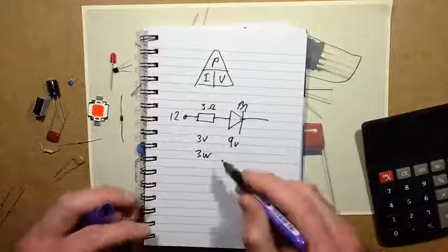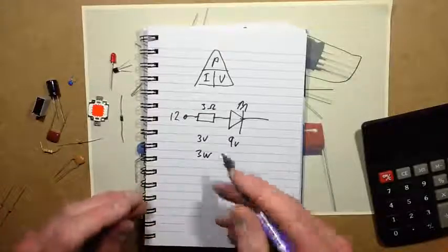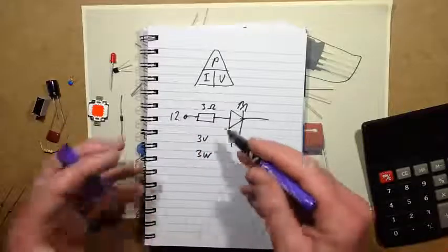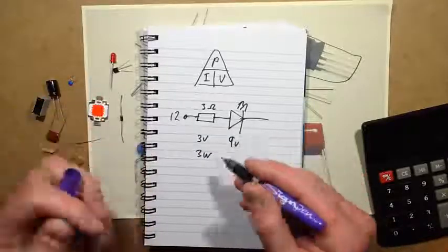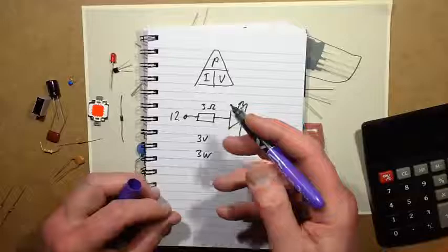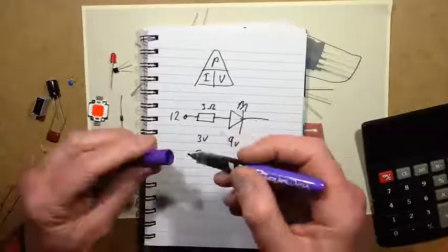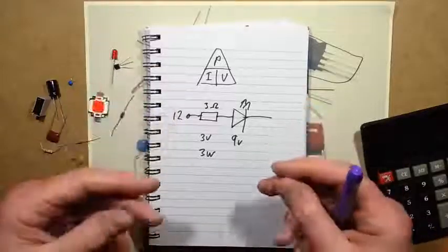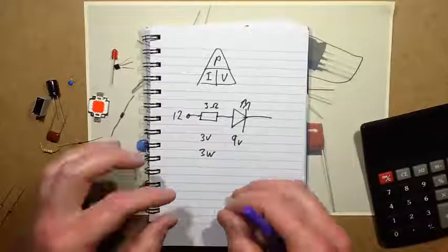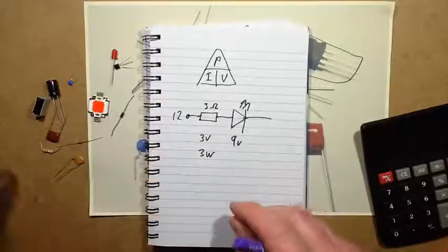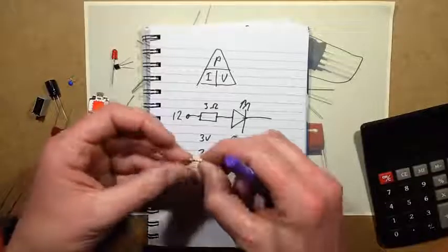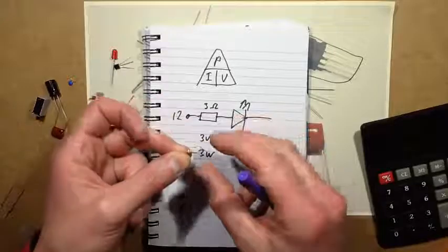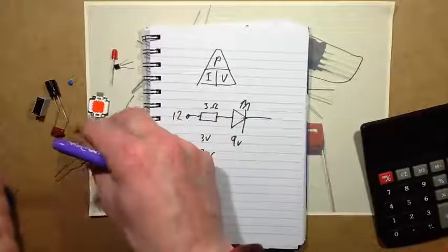But we'd actually be better choosing a higher power resistor. And it's not a terribly efficient way to drive the LEDs, but it works. It's very, very simple. I'd probably choose a 5 watt resistor because you want it to stay cool. You often see resistors that have just been pushed too far on printed circuit boards. They've been designed and they've said, I need a 1 watt resistor. They use a 1 watt resistor, and instead of a nice colour code, the whole thing is just brown, and the circuit board shows heat around it as well. So it's good to get rid of that heat.